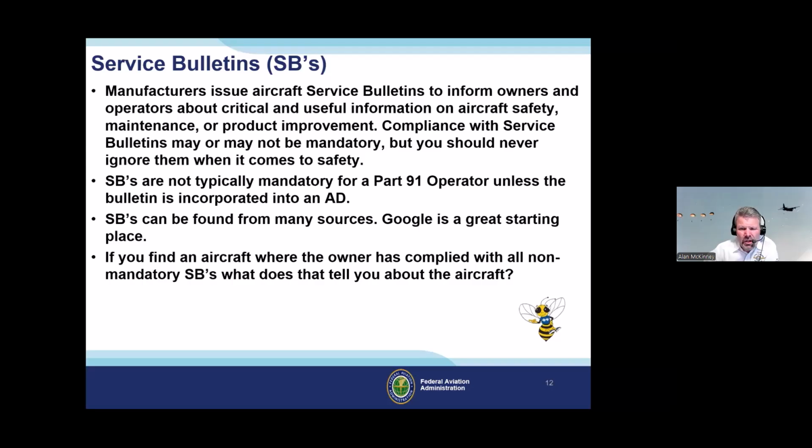If it says something along the lines in the AD of other sources or other resources are service bulletin this, that's not mandatory because they just reference it as another resource or more information or supporting information. However the AD words it, that's not necessarily mandatory. But if the inspection criteria is, then that's going to be.